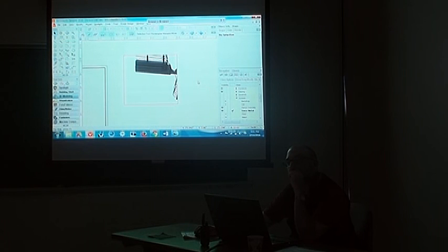Right. Because I can't see myself as I'm drawing. You do have to be thinking about it a little as you're going. Like, oh, I should create a new class for this new object that I'm building. I find myself doing that all the time. I'll have the electrics layer active with the set visible, and I'm making set changes because they're all show, snap, modify. But that set element ended up in the light plot. You want at least a little care on what is active when you start drawing something. That was something I learned as I was continuing. I do it less now.